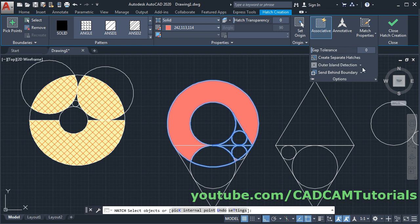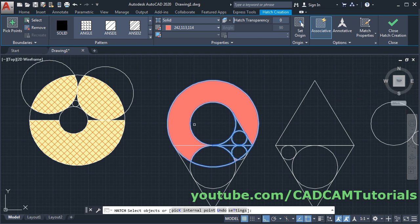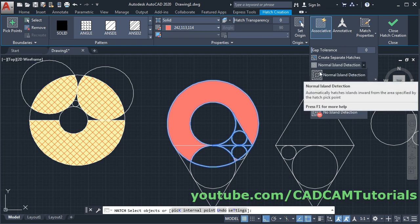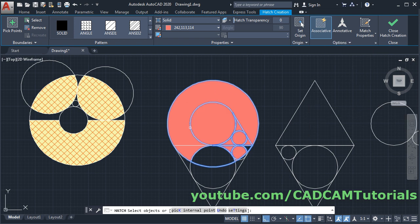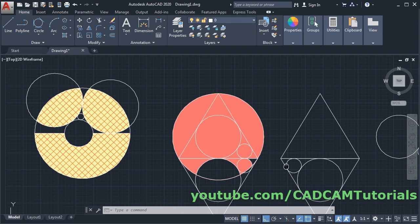Same way, if you click on this arrow and select this normal island detection, then in this case it will not make any changes. But if you are inside loops, then it will give hatch to alternate loops. And if you don't want to consider any objects, then click on this ignore island detection. So it will hatch all the objects. Then click on OK. So in this way the hatch is created.